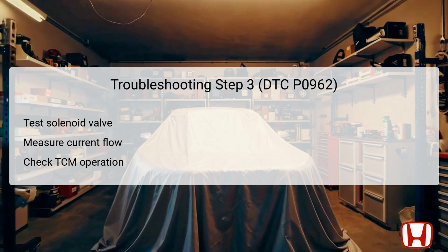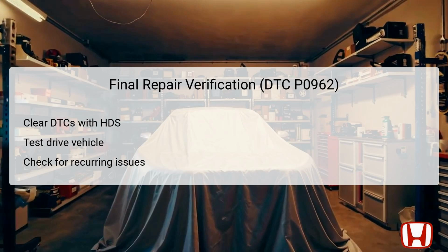Additionally, checking the operation of the transmission control module, TCM, is crucial. The TCM should reliably interpret the current readings and adjust the duty cycle output accordingly. If either the solenoid or the TCM shows abnormal performance, it will directly contribute to triggering the DTC, requiring component replacement or repair.